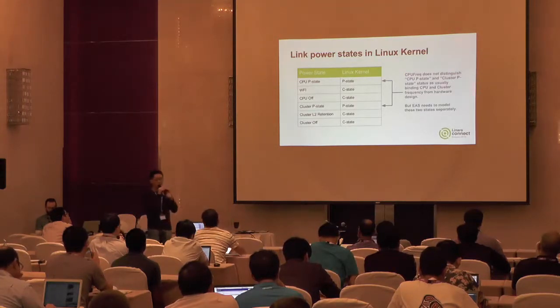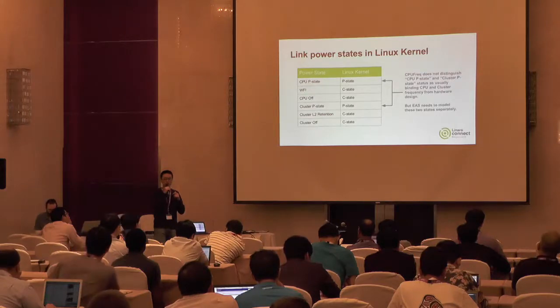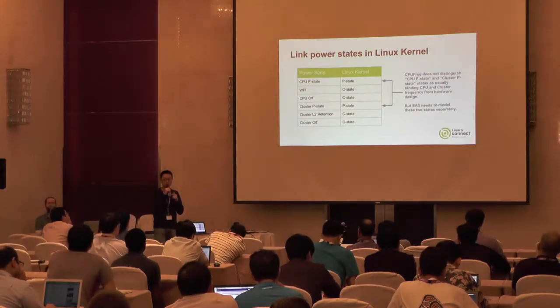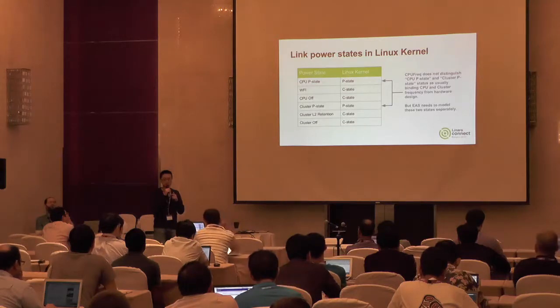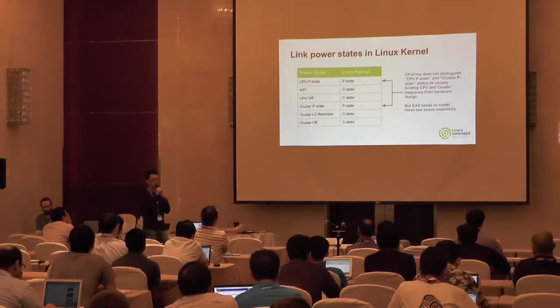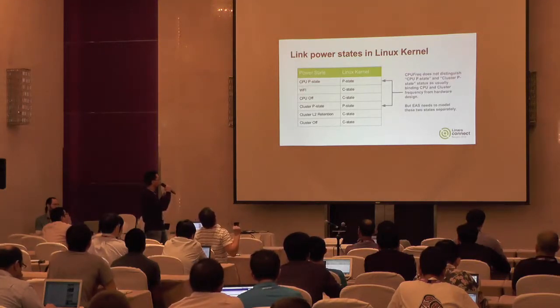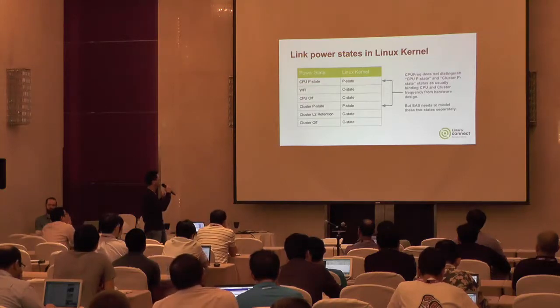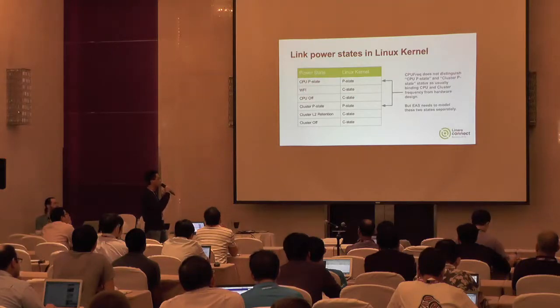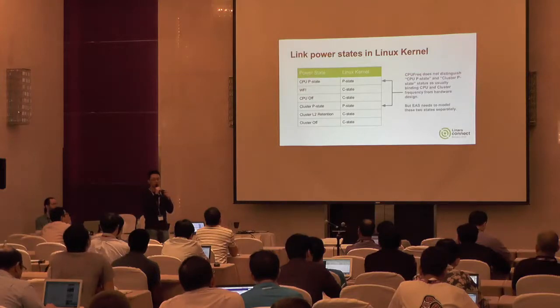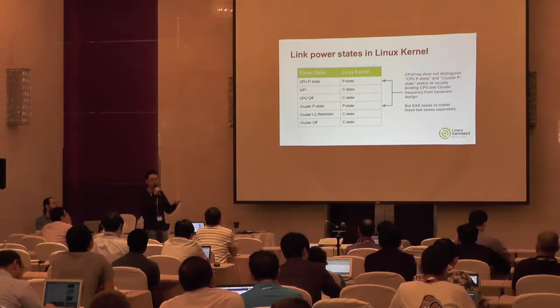For the C state, usually we use the CPU idle framework to manage these idle states. There we register into the CPU idle framework the CPU level power states, for example the WFI and CPU off. We can also register the L2 retention state or the cluster off state. But for HiKey, in this case, we just register three idle states: the WFI, CPU off, and the cluster off. We don't enable the retention state.